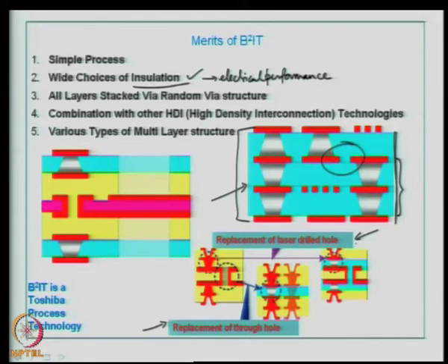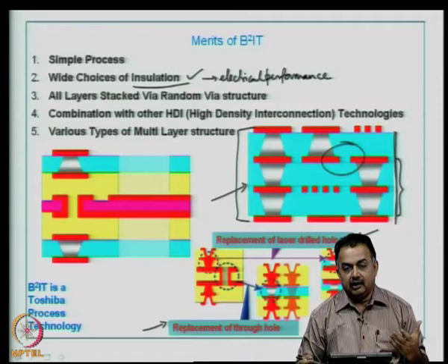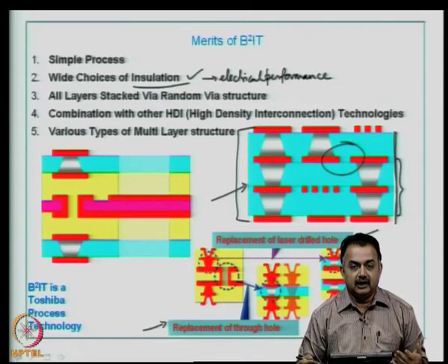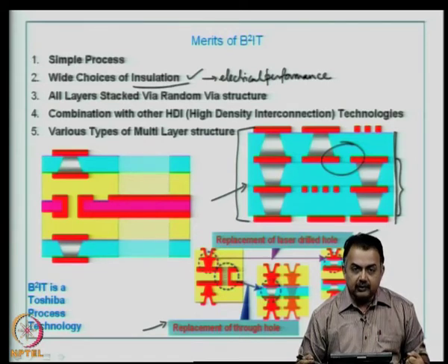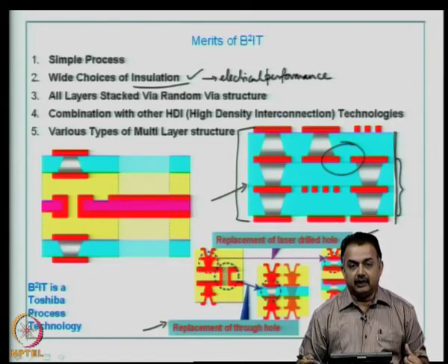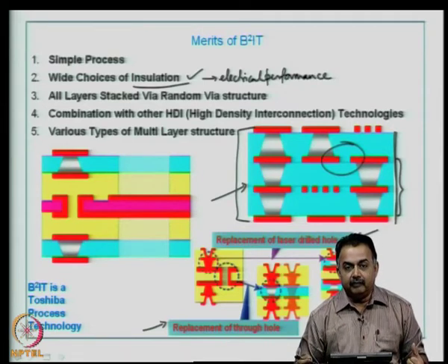This is a system level structure that we are building that can accommodate flip chip, BGA, CSP, QFN packages and so on. So, B²IT is very ideal for handheld products where there is not too much of a power dissipation that you can expect, and the sizes are typically fairly small enough, so that the construction is of high yield.